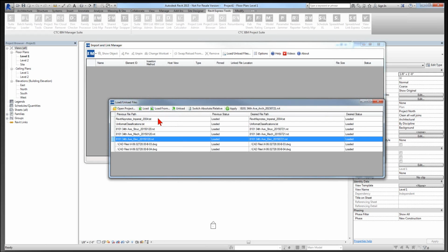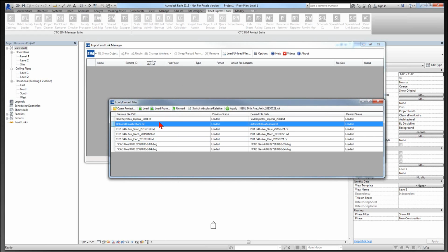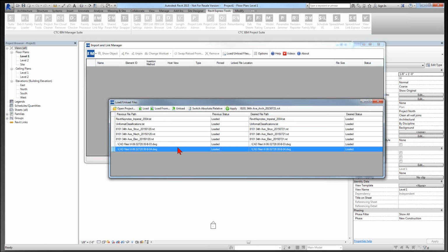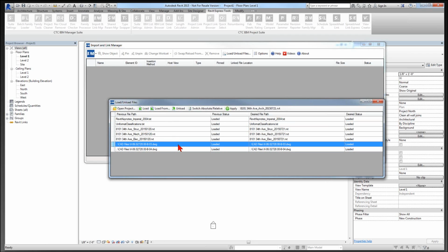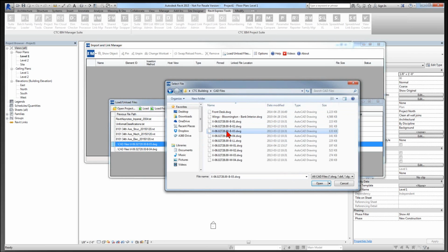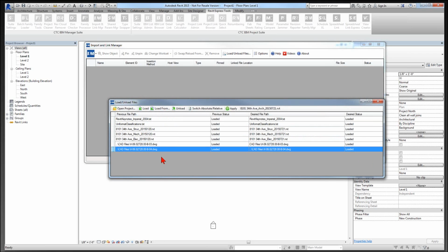So I've got that. Now, if I did want to change my unit format classifications or my Revit keynotes up here, I could change them as well if those weren't relative paths. And then there's also a couple of linked DWGs here. Since I'm in this interface and those are linked, I could choose to go in here and reload those from as well. This is a B03, so I could go here to my CAD files and find the B03 drawing file and just update that path so it knows where it's going, which is the CAD files folder.